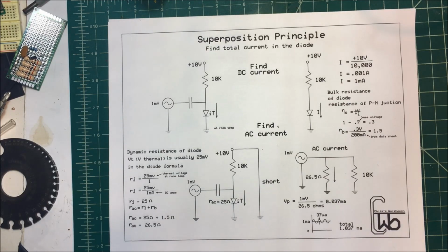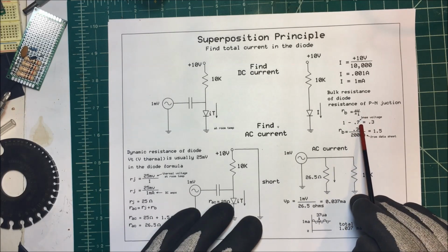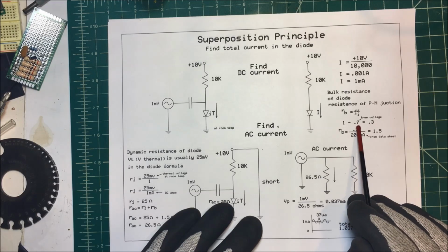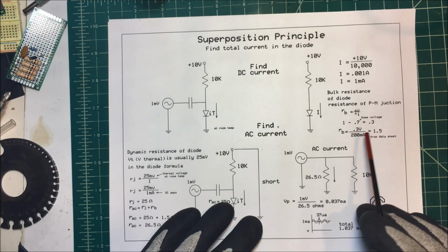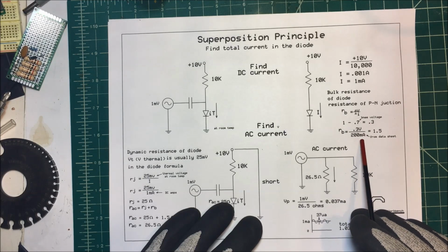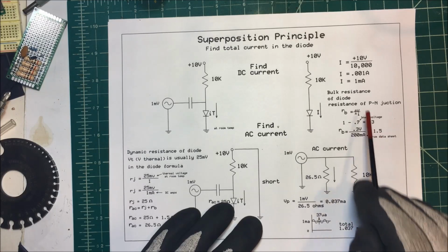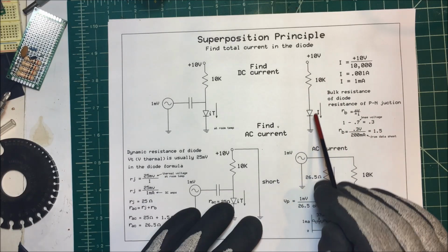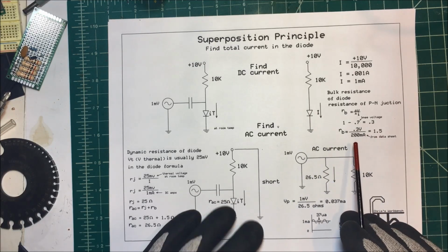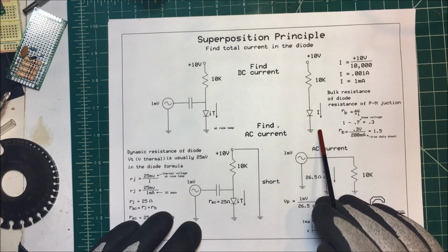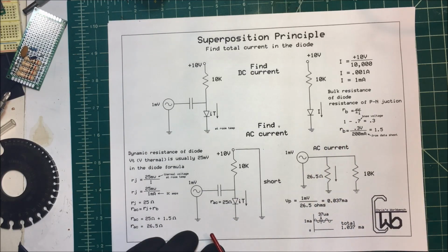So we take this change in voltage. Now, we're going to have to subtract the knee voltage, our 0.7 volts. So it leaves us with 0.3 volts, and we divide that by our 200 milliamps, okay? That gives us 1.5 ohms. Now, 10K is orders of magnitude greater than that, so we can forget about that in our DC analysis here. Let's take a look at the AC.